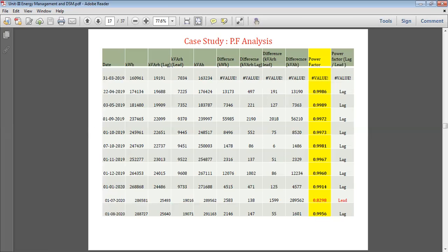So the power factor analysis itself indicates that we are maintaining the power factor very carefully, and it is close to unity. And when the power factor is close to unity, definitely the losses in the system, distribution losses, overheating problems, failure of connections because of the overheating, and failure of MCCBs, MCBs and circuit breakers will be smaller, and again it will give a remarkable reduction in the electric bill. So power factor maintenance is very important.